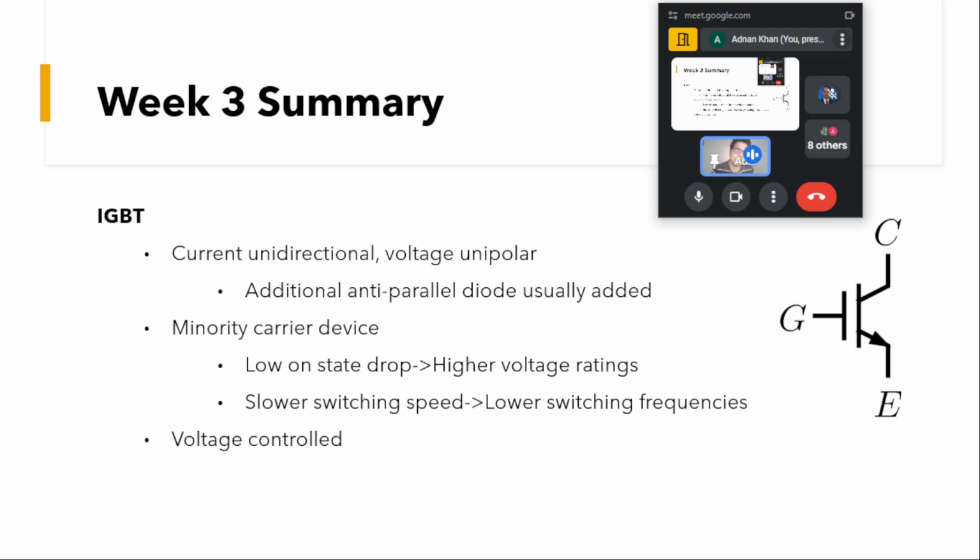But being minority carrier devices, during the turn-on and turn-off process there will be some tailing current towards the end, which we will subsequently see in the switching characteristics.